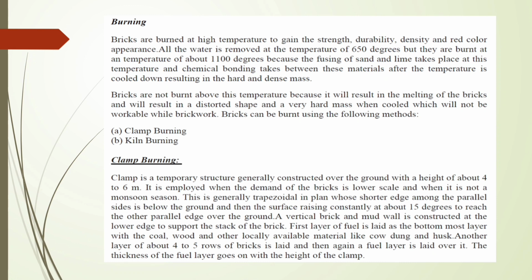It is generally trapezoidal in plan, whose shorter edge among the parallel sides is below the ground, and the surface rises constantly at about 15 degrees to reach the other parallel edge over the ground. A vertical brick and mud wall is constructed at the lower edge to support the stack of bricks.